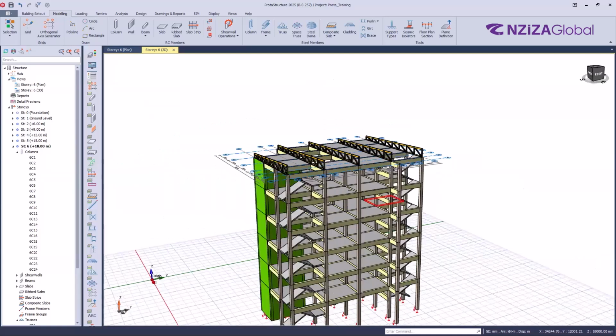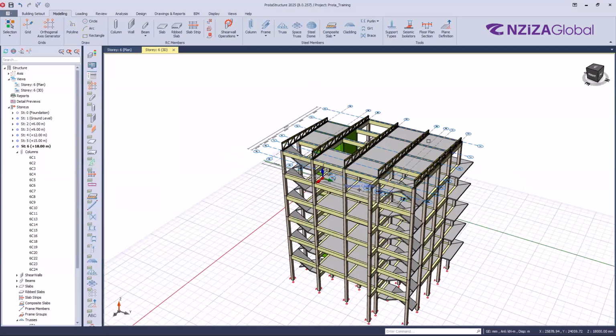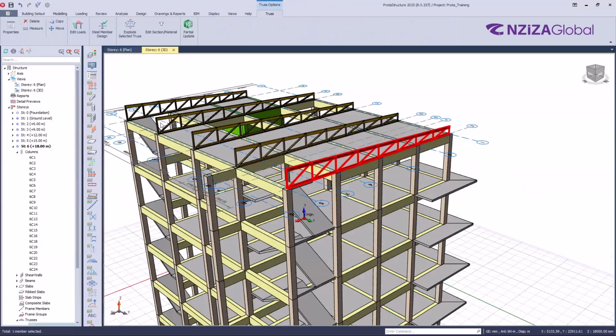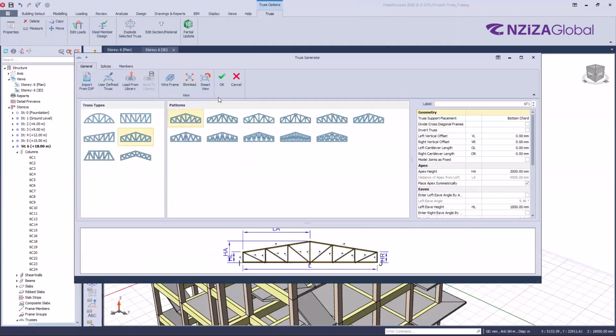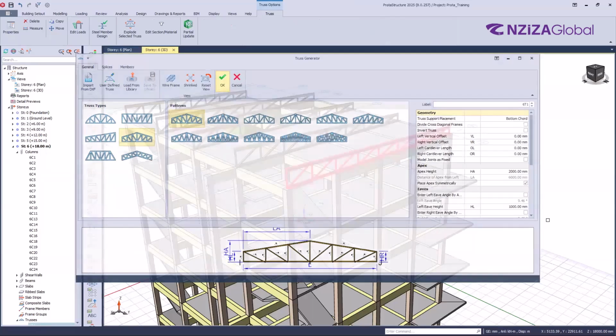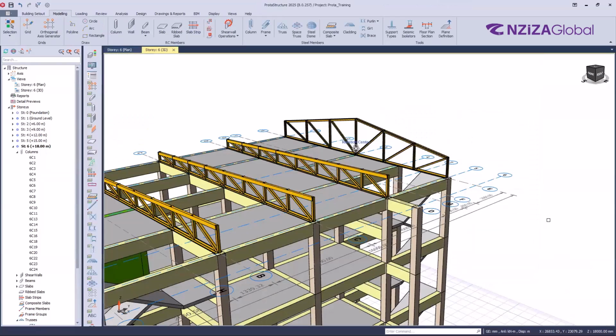If I want to modify one truss, let's say maybe this one, it's a matter of just selecting the truss, right click, and going to property, again to open this kind of property. Then you can change, maybe let's say like this, and then it will be looking like this, if that's what you want to achieve. So you can still modify trusses at any time.